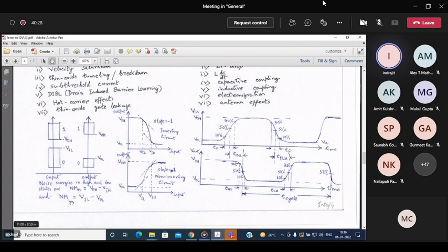Similarly, NM with a subscript L. What do we mean by that? That means on the output of a gate, the voltage level is say some value VOL. Now, again, as it travels through interconnection wire, and some positive going noise occurs on top of that, it can bring up the voltage level, and if it goes maximum up to VIL, it will be tolerated. So with the VIL, as it appears at the input of the next gate, it will be taken still as a logic low signal. But if it goes beyond VIL, then some wrong interpretation can take place.